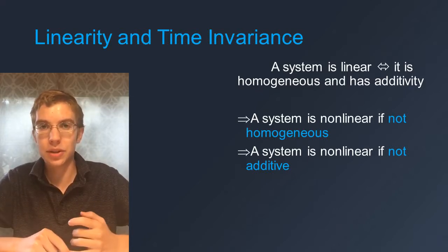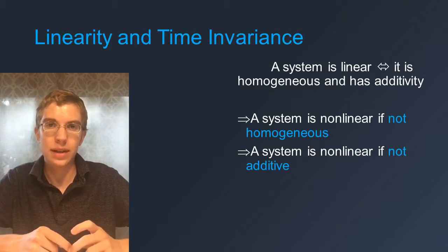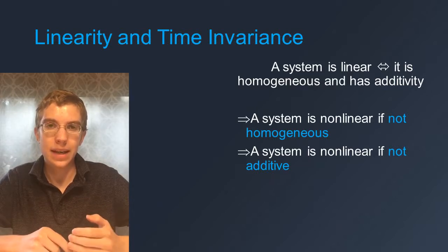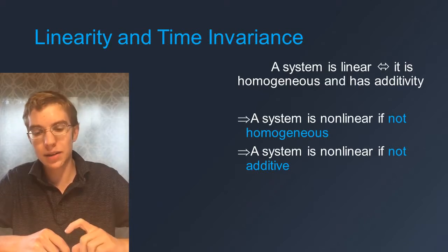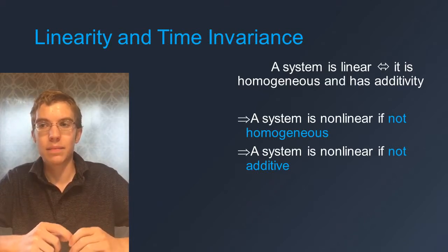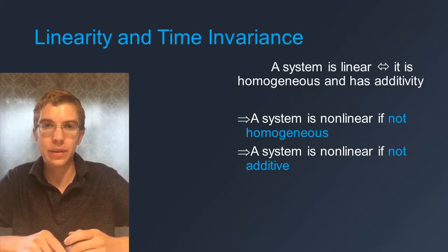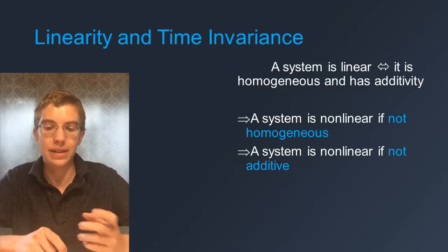behavior by observation. At time equals 0, the capacitor is going to have 0 voltage across it, and at time infinity, steady state, we're going to see that the voltage reaches a maximum. In between, there's going to be an exponential characteristic that follows the time constant of the system, and that's just going to be the equivalent resistance at the capacitor and the capacitance of the capacitor itself.